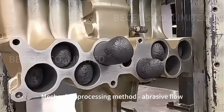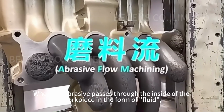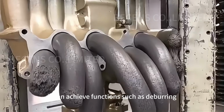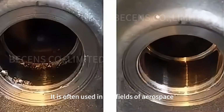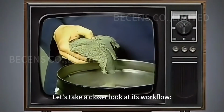Mechanical processing method: abrasive flow. When the abrasive passes through the inside of the workpiece in the form of fluid, it can achieve functions such as deburring, flash removal, rounding, and polishing. It is often used in the fields of aerospace, textiles, hydraulics, and engines. Let's take a closer look at its workflow.